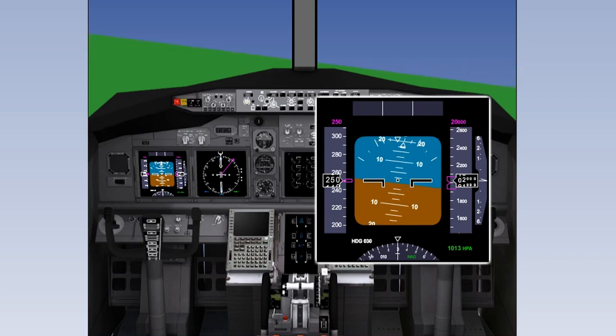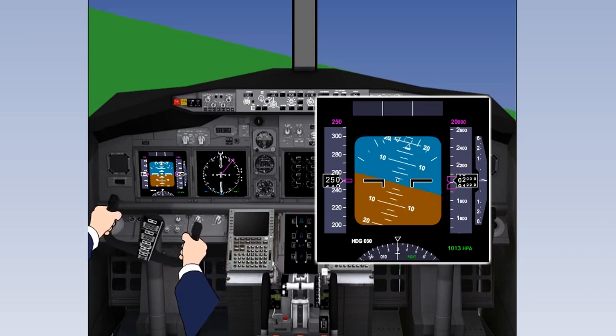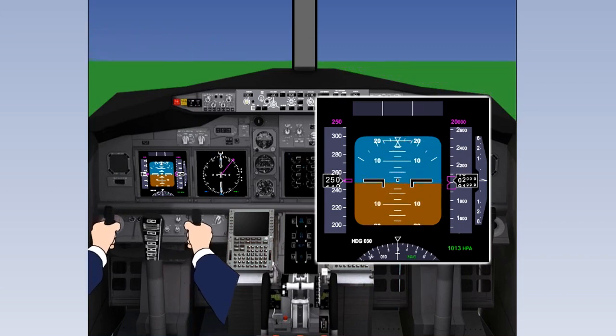In the event that a gust displaces the right wing upwards, the change in attitude will be noticed by you. By looking at your reference value, you will be able to mentally assess the rate and magnitude of the displacement. That will then allow you to mentally calculate the correction required to bring the aircraft back to wings level, and apply that correction to the controls. Having made the correction, you can see the aeroplane moving back towards wings level. When the aircraft is back to the required attitude, the control input can now be removed, and the controls set to neutral.